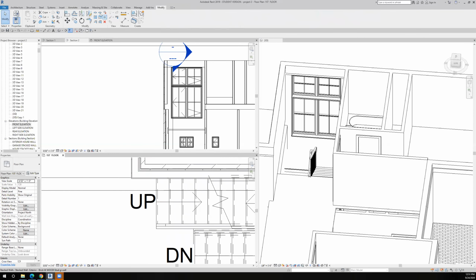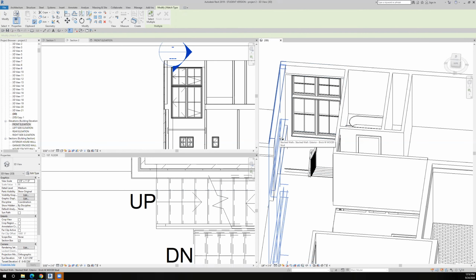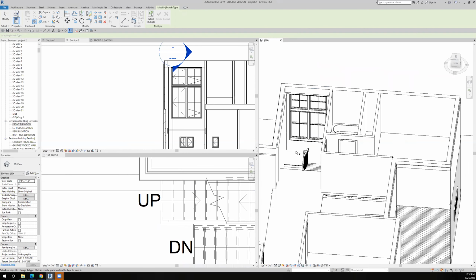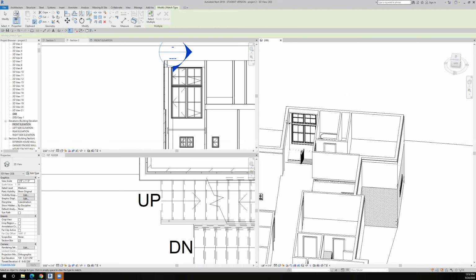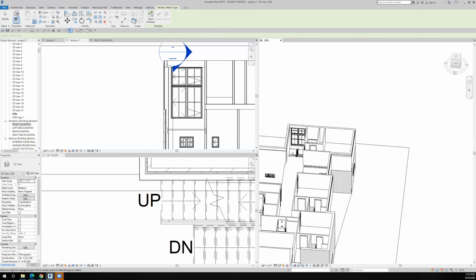So I'll go over to modify, then I'm going to say that the wall type changes right there. And then I'll use the match properties. I'll match this and this because I want it to be a full flush height of gypsum board on the inside, where it's flush all the way from the first floor all the way up to the second floor. There isn't a pocket for the floor joists to fit into because there are no floor joists. So, okay, that was a little bit of a cleanup.